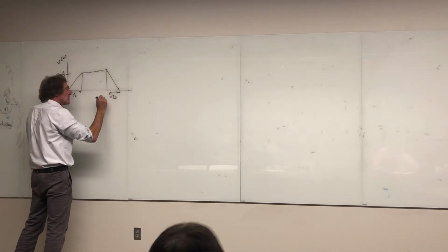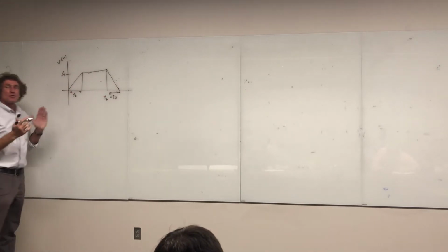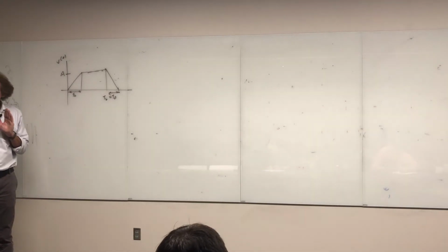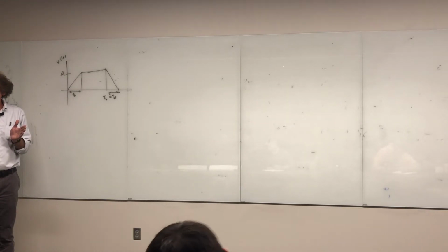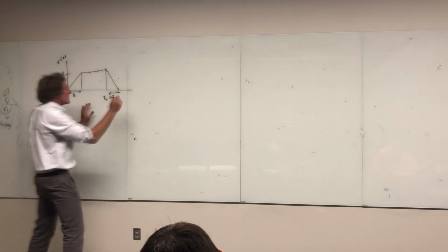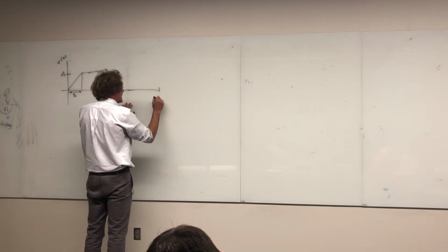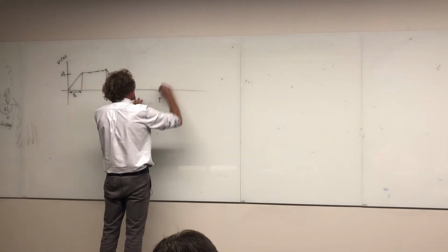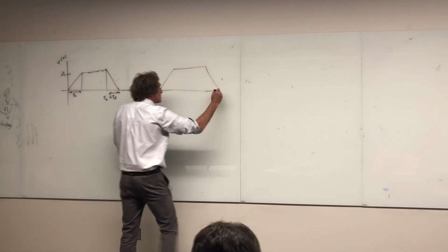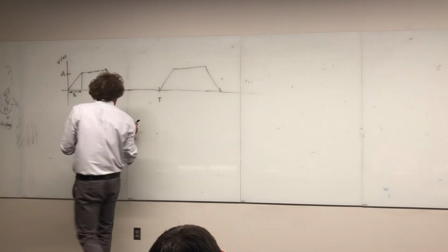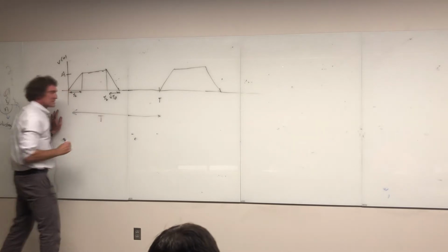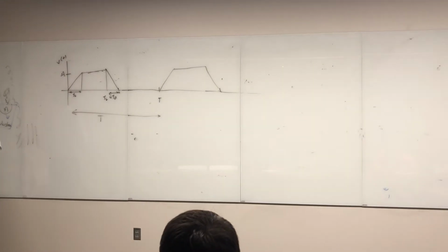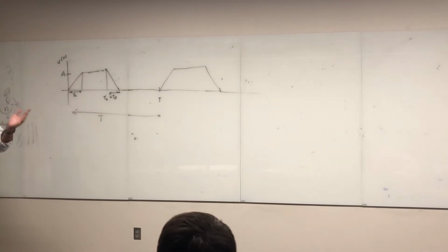Almost always, we take the shorter of the two and use that, all right? So we make the rise time equal to the fall time. We find which one is the minimal time when we use that. Now, this repeats itself at T, and then you've got this. It just goes up, stays there, and the clock pulses repeat themselves. What's important to know is this is called the period, or capital T. It's actually the pulse repetition interval, PRI, but use capital T because most of the work so far up to now you've seen capital T for a period.